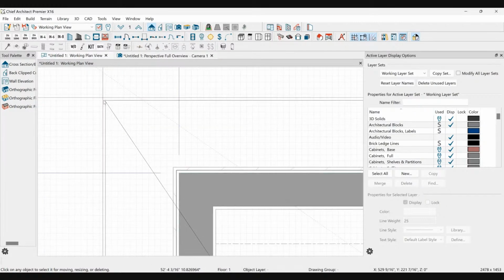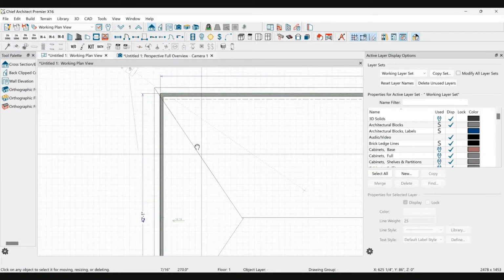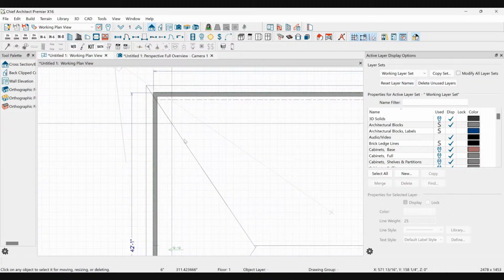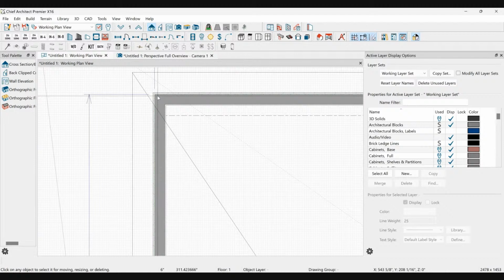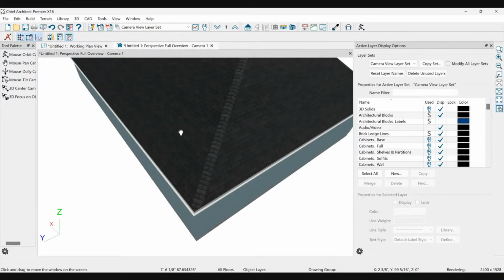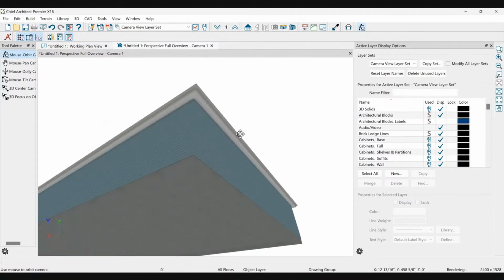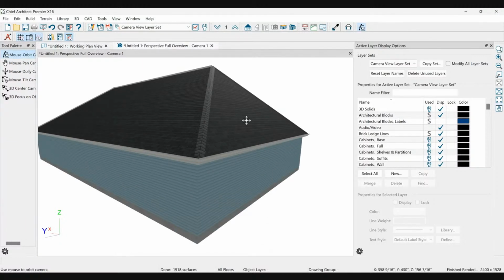In a perfect geometry world, that would not line up. And so like you could adjust the math to figure out what the number would be. But what happens is also ugly framing, because now your hip is not landing right out of the corner. So this is something I don't recommend really ever doing unless you absolutely need to, because it makes the roof geometry a total bitch. So don't recommend it, but like this is what it looks like, okay? So you have uneven roof pitches, you have even overhangs, but you've sacrificed the plate height being the same.